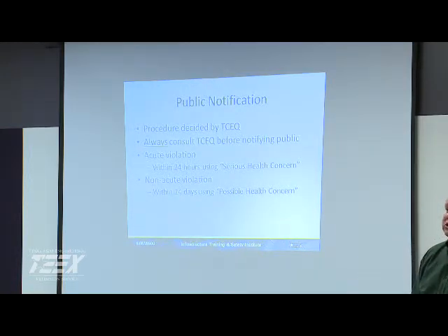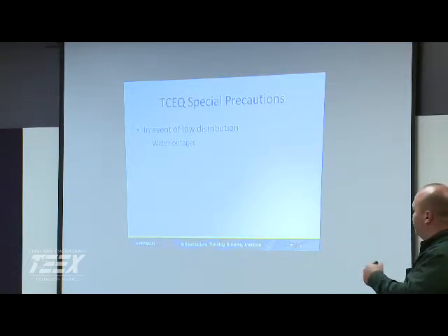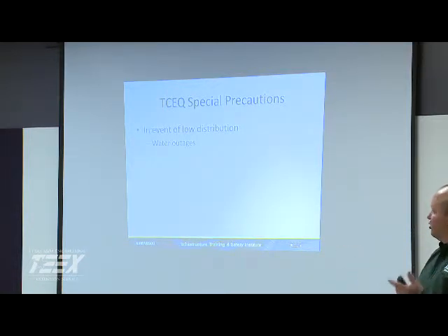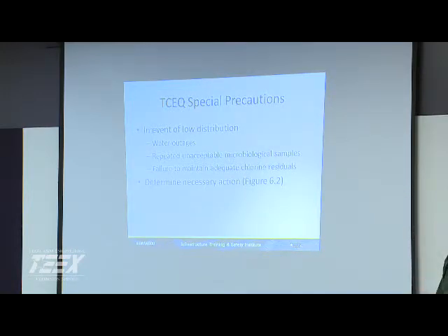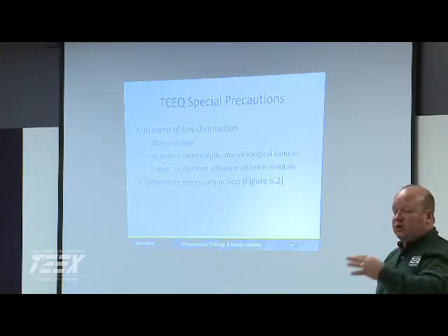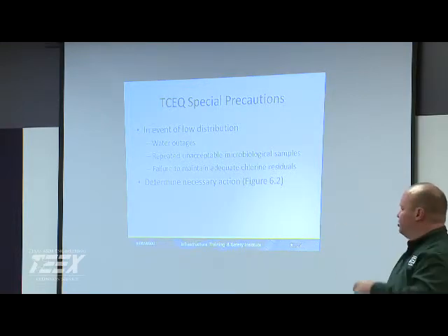Right, so basically you're going to put it on your CCR, your consumer confidence report. Even though that's for the state, and we've been talking a bunch here in Tennessee about what we consider low distribution pressures. If you do have an issue with water outages, unacceptable sample results, or you're not maintaining your residual properly, normally in Texas you've got to have 35 PSI in your system, that's normal operating pressure. You're not supposed to have below 20 under fire flow conditions or main breaks. Y'all in Tennessee are just 20, right? Yeah, that's minimum. So that's minimum. They're shooting for 35.